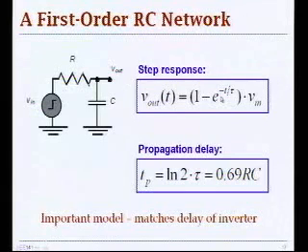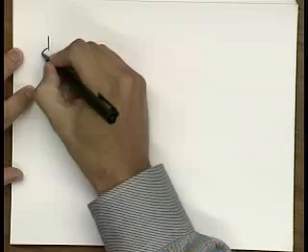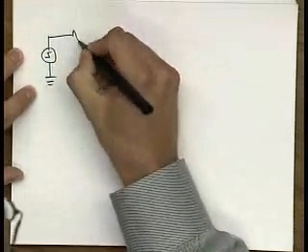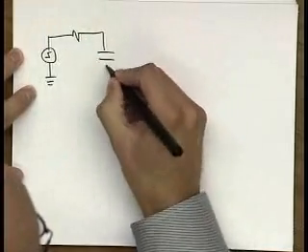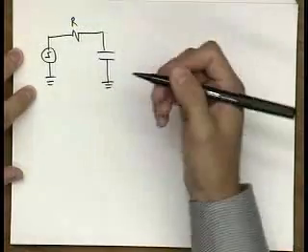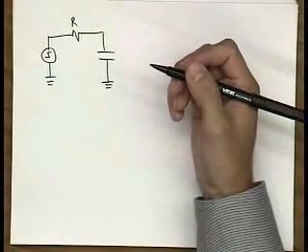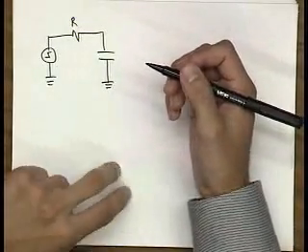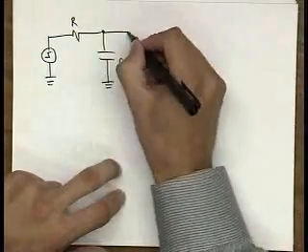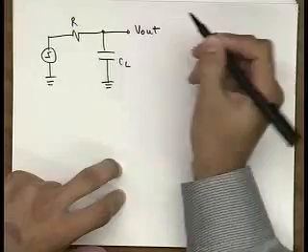And it's actually pretty easy and intuitive to derive this formula if you go back to the overhead. So you have your source over here, and then you have your RC network, with R being attributed to the equivalent pull-up or pull-down resistance of a gate when it's charging the capacitance to a logic 1 or discharging to logic 0, and you have your load capacitance CL here. So you have V out.